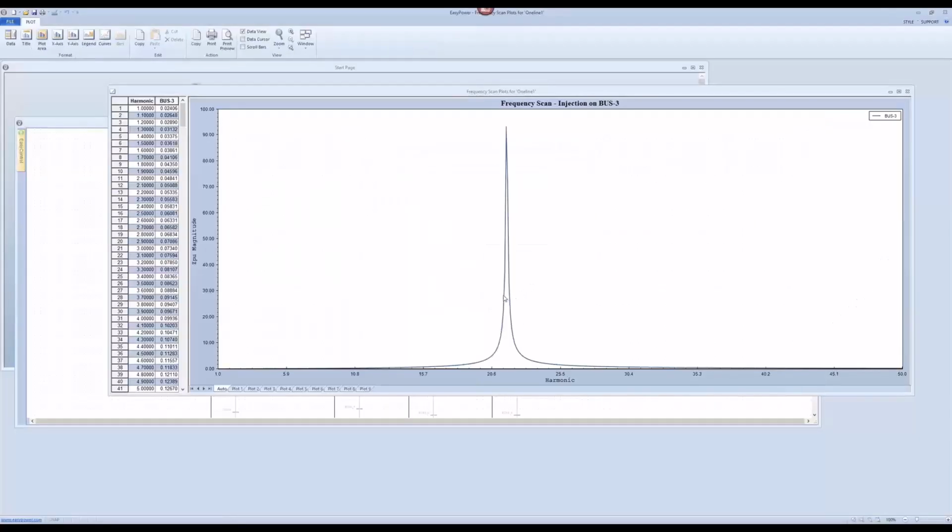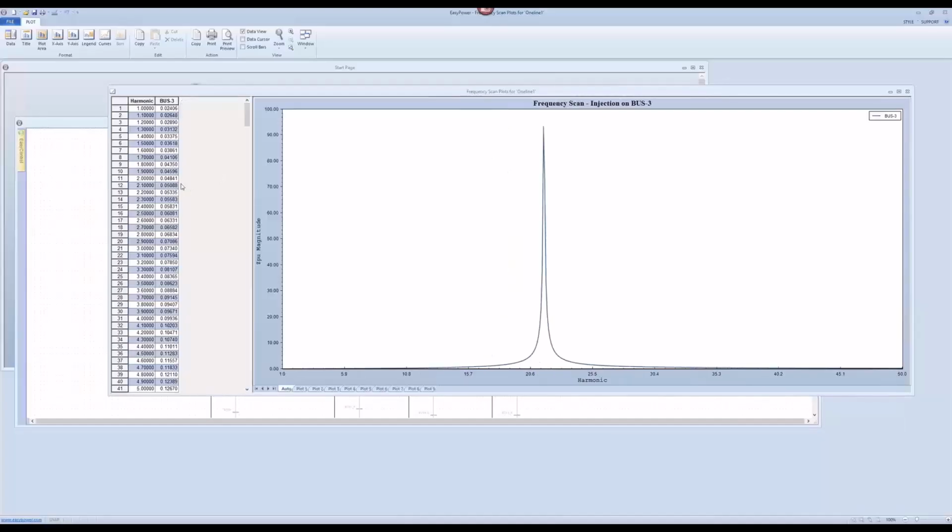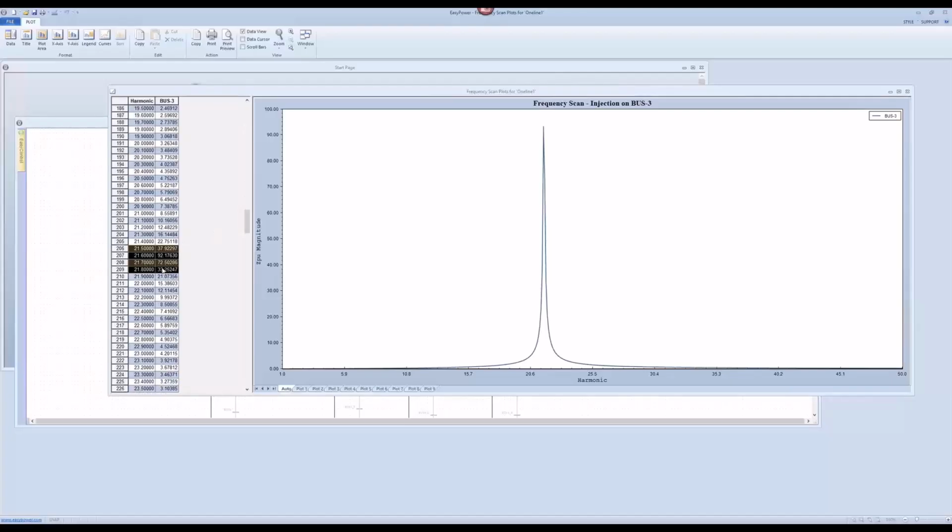We know that in my system, I do have a resonance point at 21. What is my level here? About, if you go to the left, you will see what exactly the value is, right? Okay, I do have a resonance point around my 21 to 22 harmonic order, right? So if I have 21, 22 harmonic current injection, it will be significantly amplified because I do have a spike